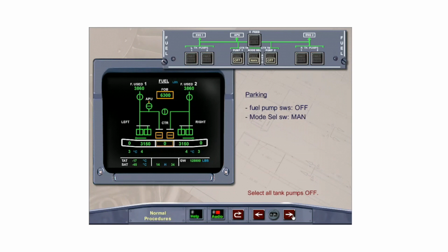All fuel pump switches are selected off, and the mode select switch is selected to manual after engine shutdown.